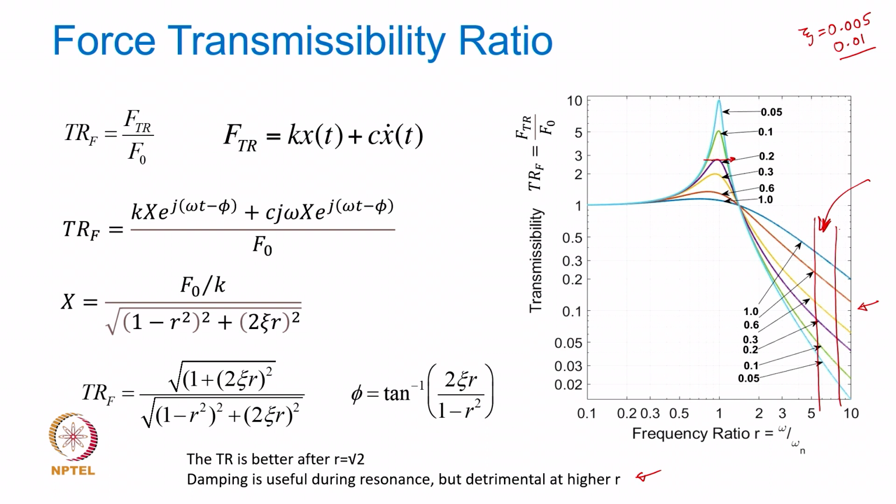But sometimes if you are coasting up rather slowly for some reason, if you cannot traverse through this resonance fast enough, then you might end up generating large excitations transmitted to the base, because you notice that even with 0.05 you are almost transmitting 10 times. Okay.